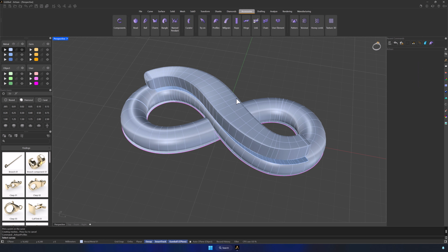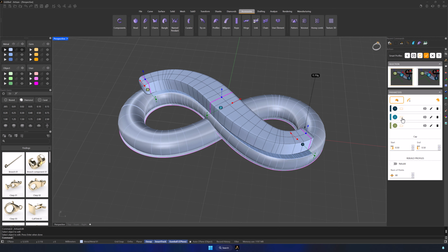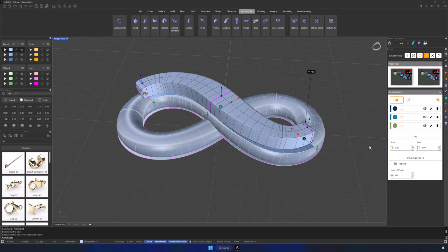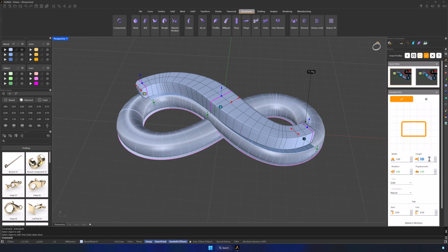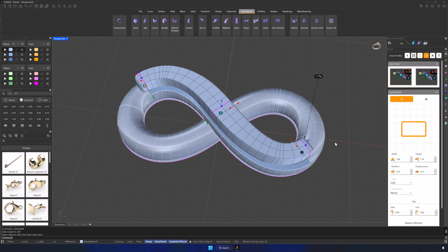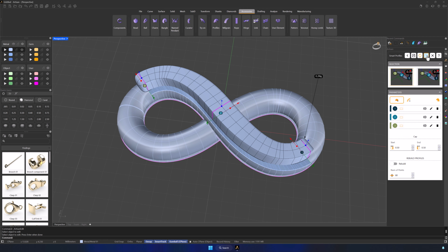I've realized that I haven't added the surface as a reference. We'll select the created profile and click on Edit, add the surface to the selector. Since the rotation is not correct, we'll select it and type Flip. Then we'll add it to the selector again to adjust the solid's position. I'll also make the central profile a bit narrower. I'll change it to 1.6 millimeters wide. Now we accept the command.